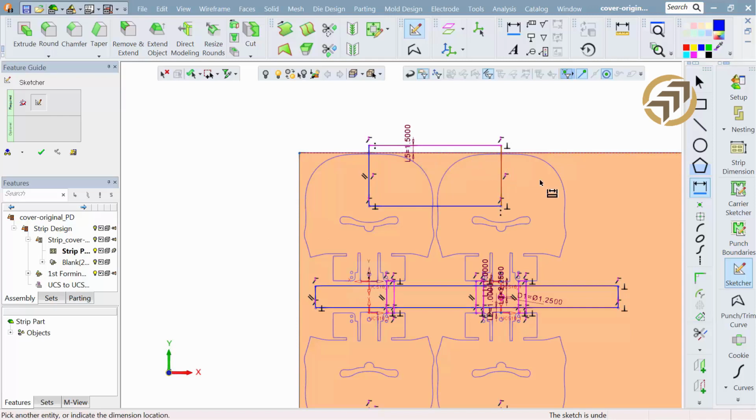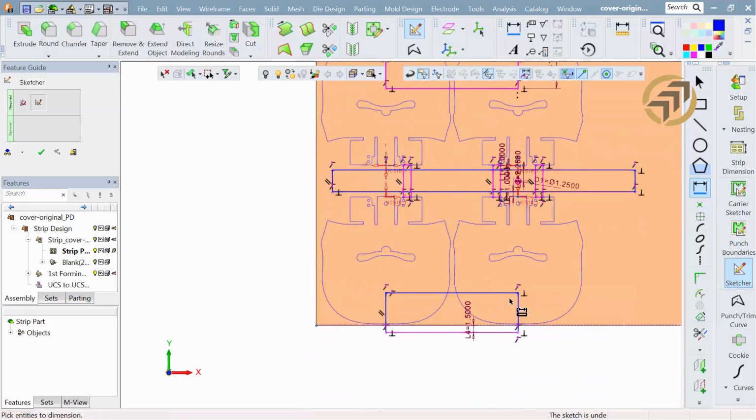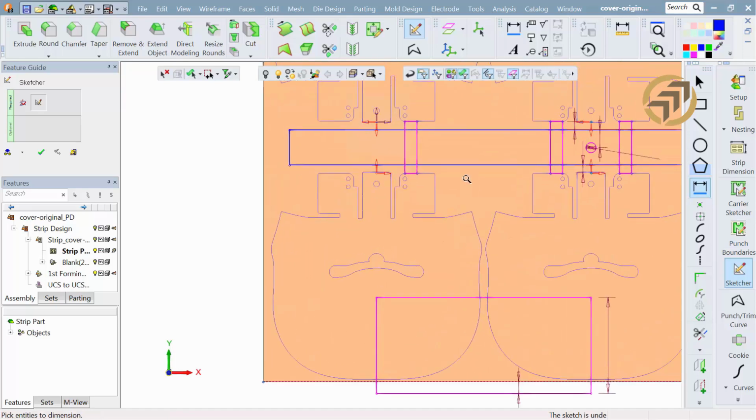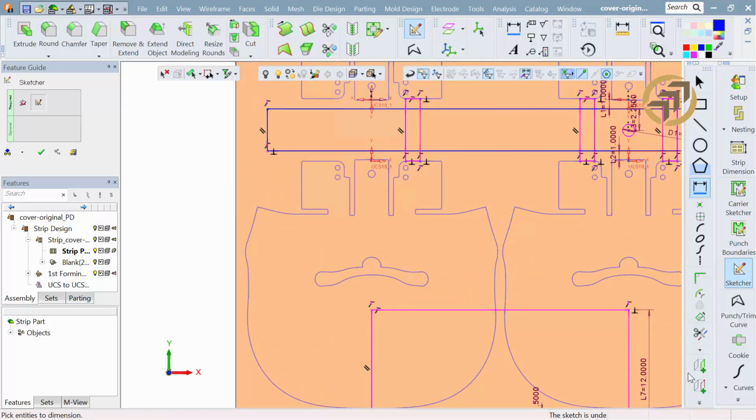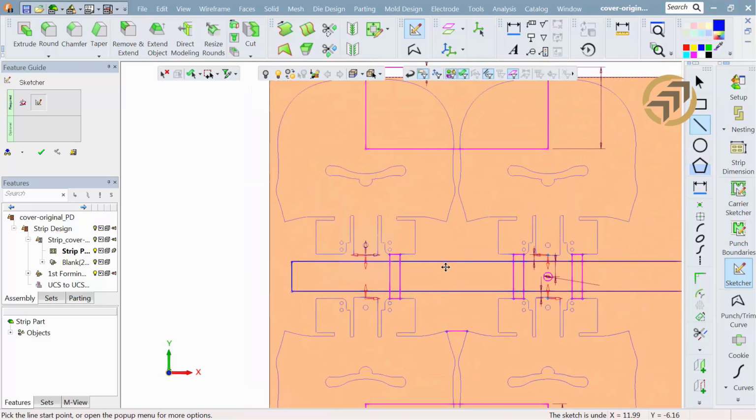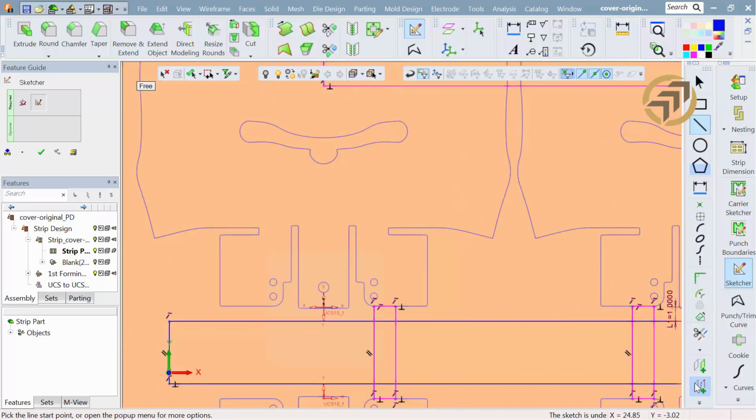Not all right hand, left hand parts are truly right hand, left hand. So whichever the preference is, particularly whatever the case is involved per each job. So again, further dimensions to show me where my punches are going to break. You notice I'm not really concerned about everything being exactly perfect. I'm not going back and trimming up overlaps in my sketch where punches occur. I'll just close that area off on both sides. That's where I'll stop those punches. That would be like the seam or the break point between those two punches.